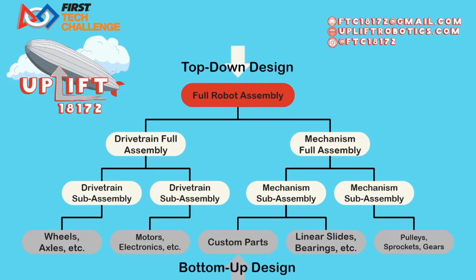One approach in CAD is bottom-up design, which starts with taking parts and combining them into larger assemblies similar to how you'd assemble things in real life. For our robots, you may start with a wheel and axle mounted to a chassis frame and then add motors and other mechanisms until you have a full robot. This is great for many applications, but if you want to change a part, then you have to make changes in multiple assemblies and other parts, which is inconvenient and time-consuming.